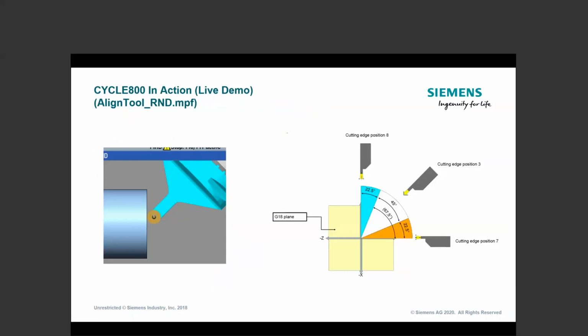Once the side cutting edge of that insert went beyond vertical or horizontal, there's our transition point, that's when we flip over. When I get to a button tool, well, when do I make that decision? So all we did was treat it as 45. We thought of a button tool as if it was a 45-degree insert.